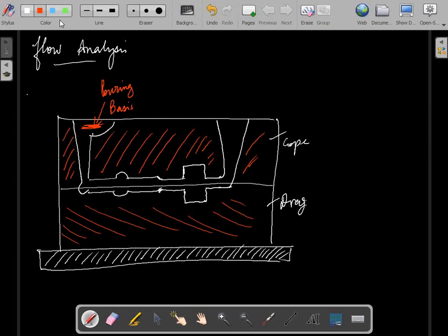So you take your molten metal and you bring your ladle on top of this pouring basin and you pour the molten metal into this. It collects over here and then it runs down this channel, which we call sprue. Okay, this taper section is known as sprue.